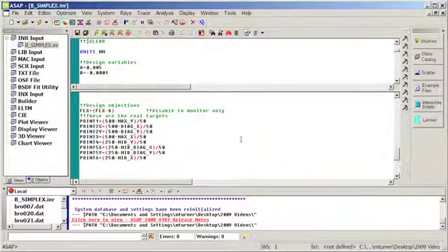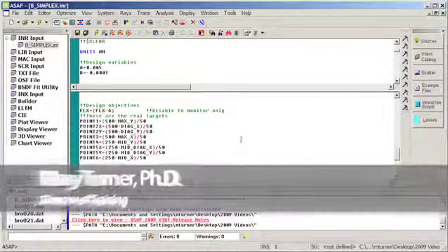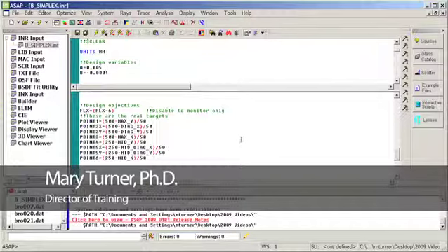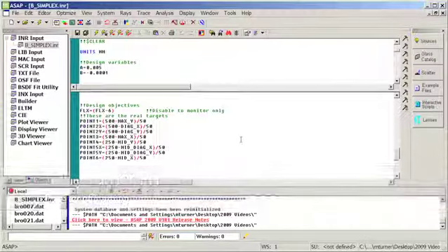A couple new capabilities have been added to the optimization function within ASAP 2009. The first item is that variables, design objectives, and penalty functions, as long as they are defined contiguously within your ASAP file, can be selected simultaneously. And the other is that the state of the optimization can be saved as a separate ASAP file, which will remove the requirement to continually redefine the variables and objectives each time you load in the file.